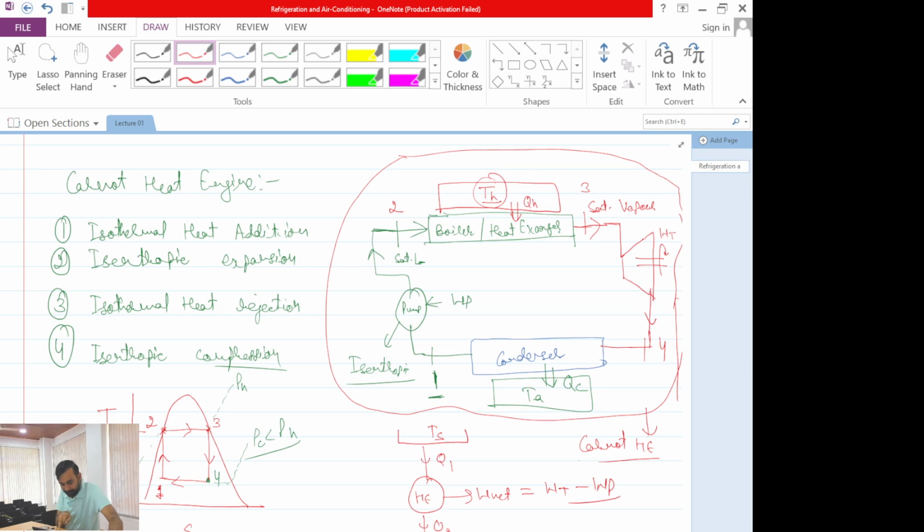First, at point 4 we have a large amount of liquid, so typically it is not good for the health of the turbine. The turbine can be damaged at a rapid rate, but if you practically want to operate, it will operate. So that is one practical aspect for the health of the turbine, but still this is not the point that makes the cycle impossible. What makes it impossible? Please tell me. Entropy is a matter of the practical cycle. If I have to operate everything in an ideal fashion, why is it not possible?